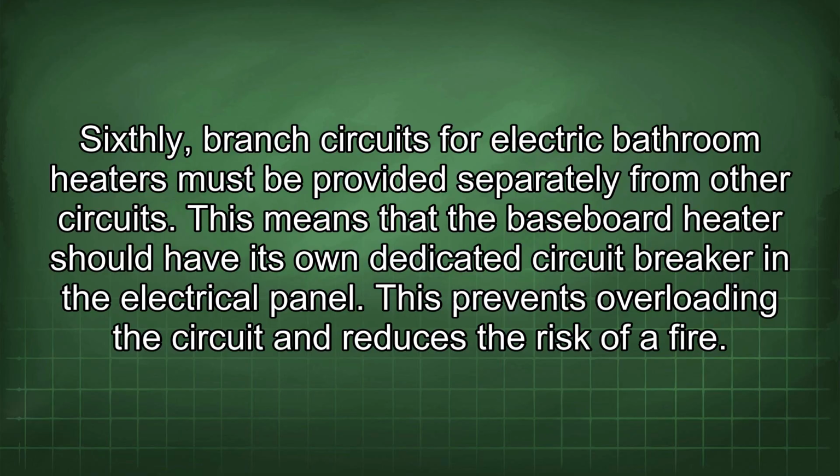This means that the baseboard heater should have its own dedicated circuit breaker in the electrical panel. This prevents overloading the circuit and reduces the risk of a fire.